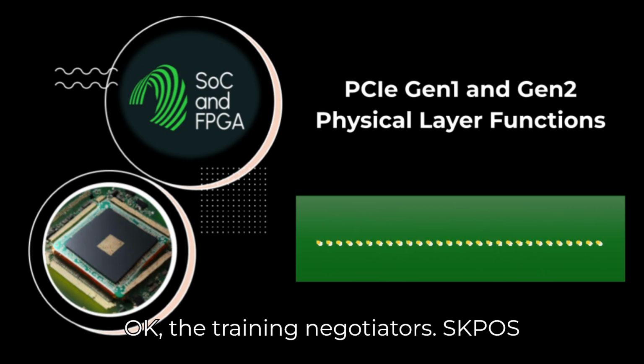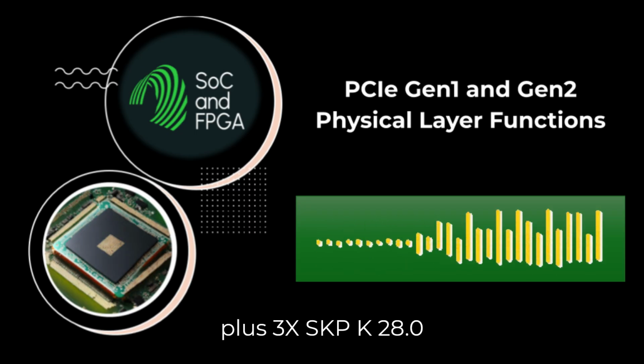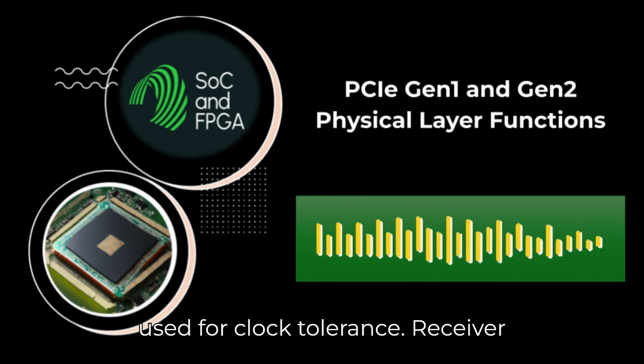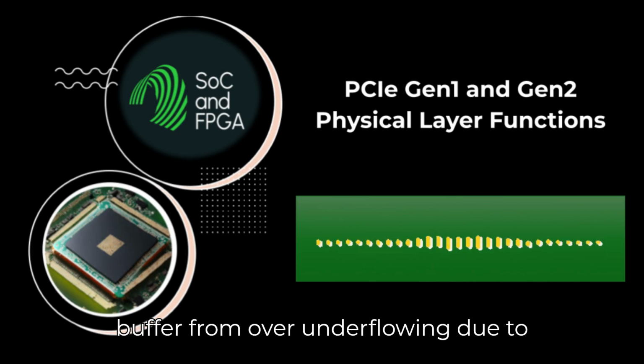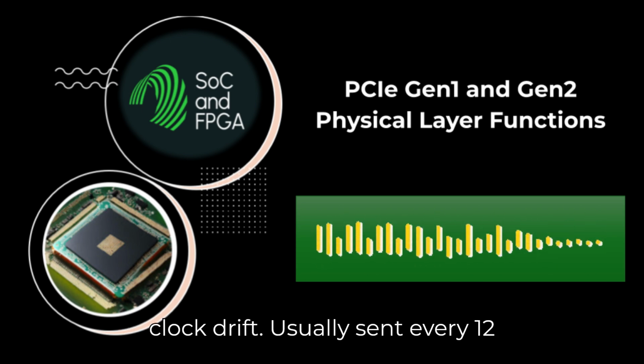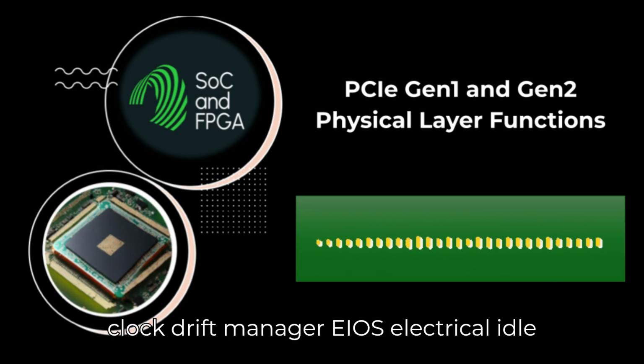Okay, the training negotiators. SKPOS. Skip ordered set, just 4 symbols. COM plus 3x SKP, K28.0, used for clock tolerance. Receiver periodically inserts these and can delete SKPs from the stream to keep its elastic buffer from over or underflowing due to clock drift, usually sent every 1200 to 1500 symbol times or so. The clock drift manager. EIOS.